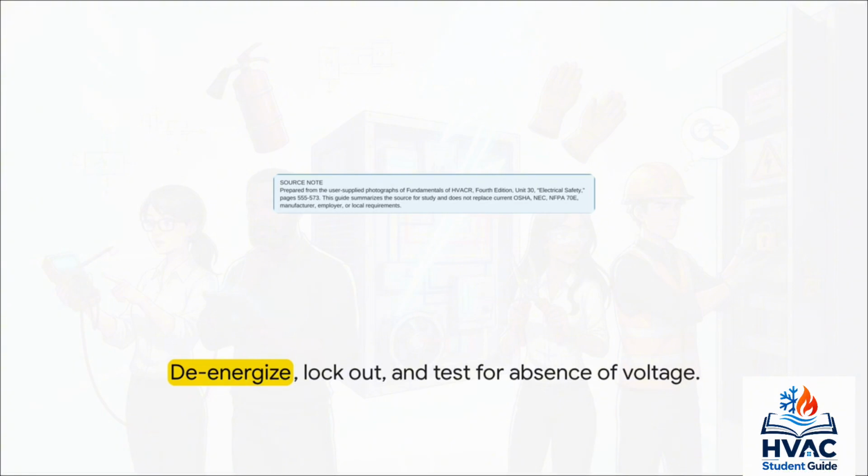Honestly, if you remember nothing else from this explainer, make it this cardinal rule. Whenever humanly possible, work on a circuit only after it is de-energized, locked and tagged out, and tested for the absence of voltage. You verify your meter works on a known live source, you test the equipment to prove it's dead, and then you retest your meter. That is how the pros stay safe.